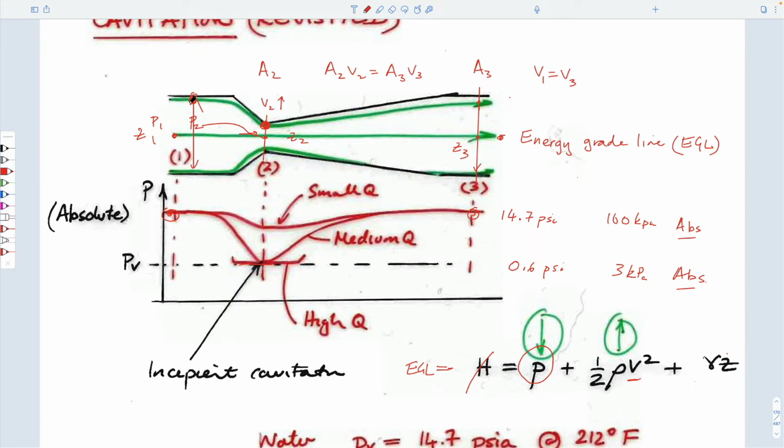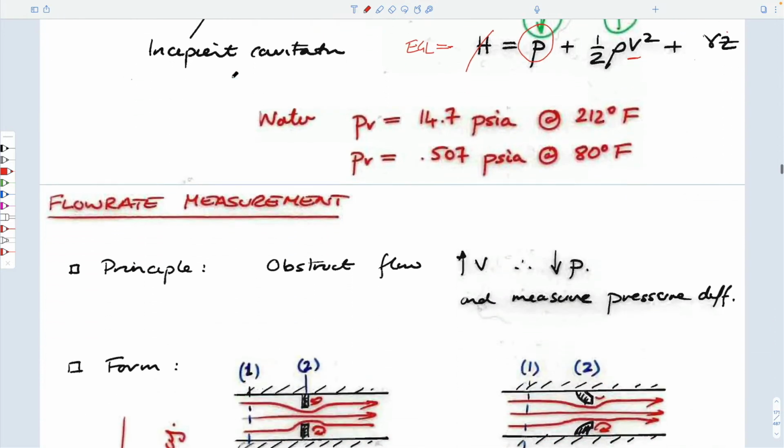So you can get values for those, but it's not as accurate as using what's called a differential pressure transducer. You can buy them. They use PZTs, and what they do is they link the two locations, upstream and downstream, and physically give you a readout electronically of the difference in pressure, delta P, not the absolute pressure at those 2 points. And it turns out to be much more accurate to be able to do that.